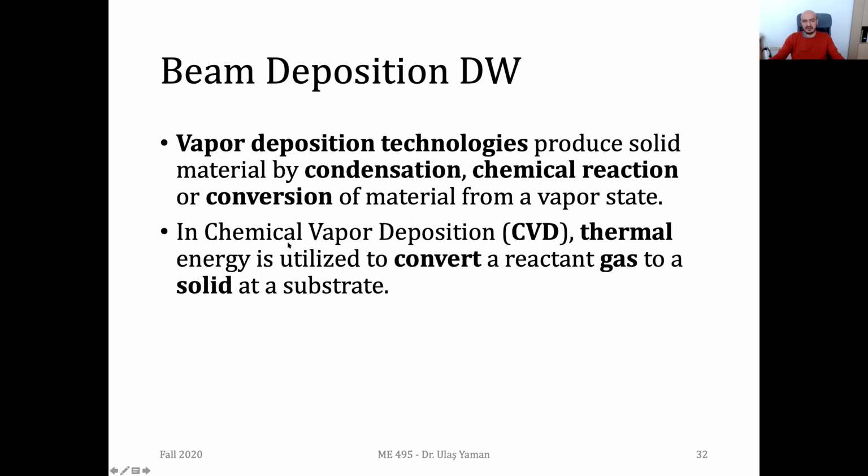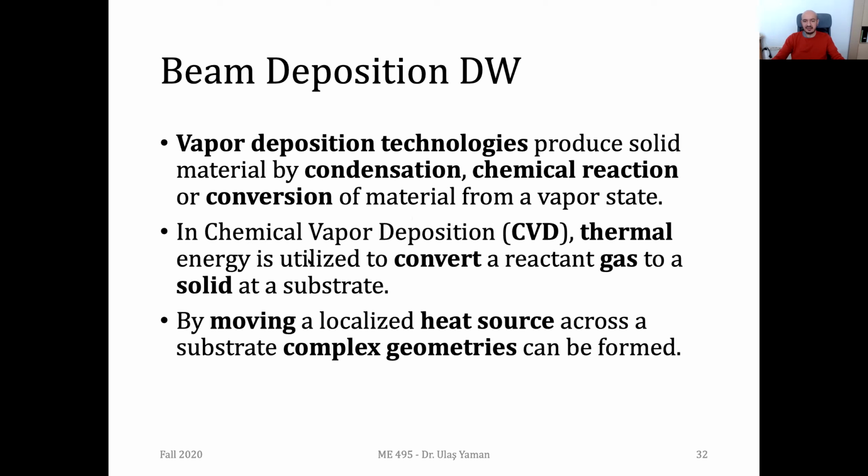And the most fundamental, the most popular one is the chemical vapor deposition. We are using thermal energy to convert our gases into solid particles. And then once you obtain these little particles, they can be deposited on different parts. And that's a very nice technology, and it's mostly utilized for coating cutting tools. The tip of the cutting tool, for instance, might be deposited with titanium carbide, and this is done with chemical vapor deposition.